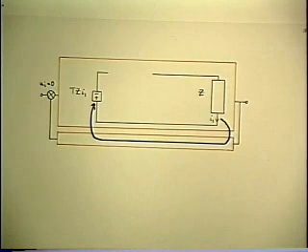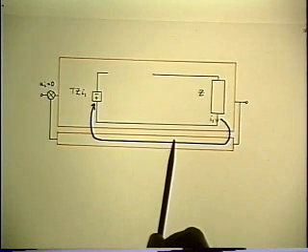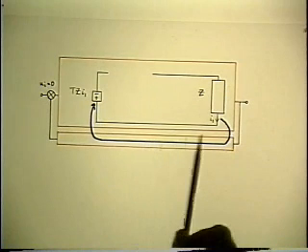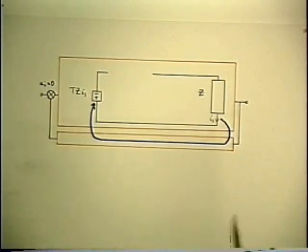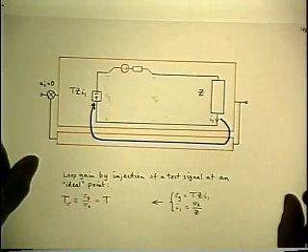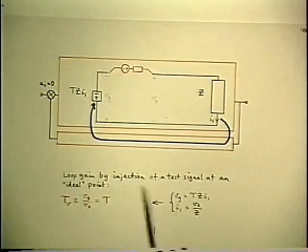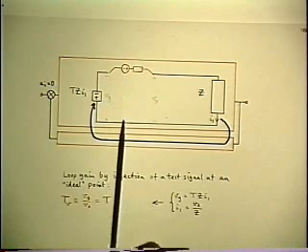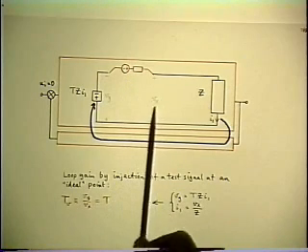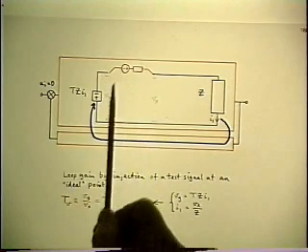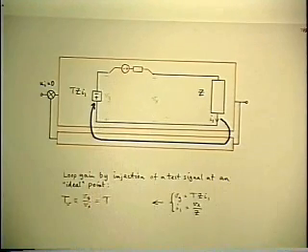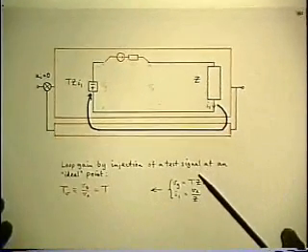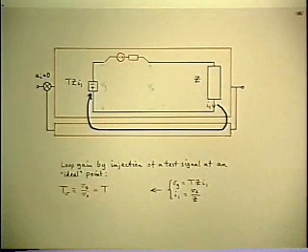But we do want to get into the problem where we start the right parameters that we want in the answer. So if we're going to do voltage injection at an ideal point, we've already shown this is equivalent to breaking the loop and applying the voltage at the same point. It's ideal still because we have a zero impedance out here. The first parameter to get into the answer is the loop gain, because that's the answer ultimately we're looking for.